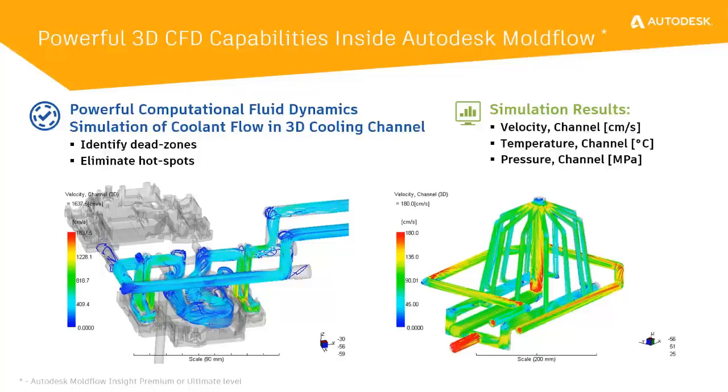Historically, what we have seen is these unique conformal cooling channels were designed and simulated using a standalone CFD tool to validate coolant flow rates, turbulence, and pressure drop through the circuit. What was missed is the impact the cooling circuit has on the mold temperatures and ultimately how the part will shrink and warp with the conformal channels. Moldflow now allows this connection to fully explore the advantages conformal cooling can provide.